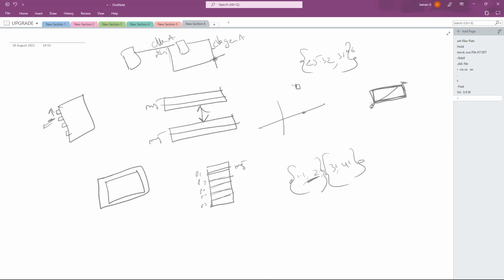Okay, inside the macro, what the metal layers are and how they got routed is not your problem. Only the routing over the partition is your problem. That is the thing. Inside the macro routing, the analog layout people will be doing all this stuff.